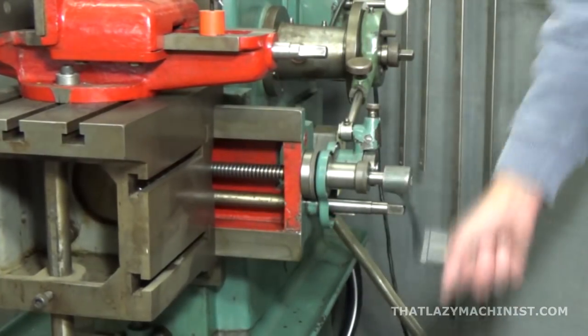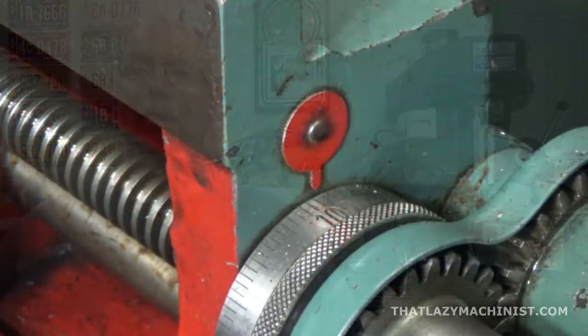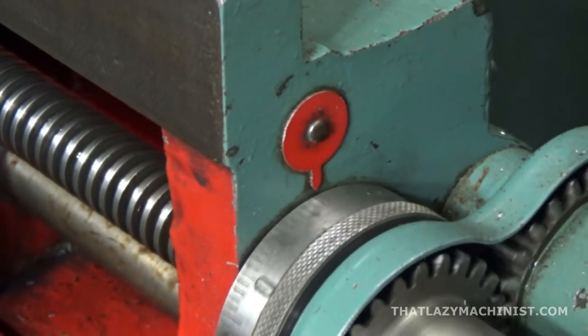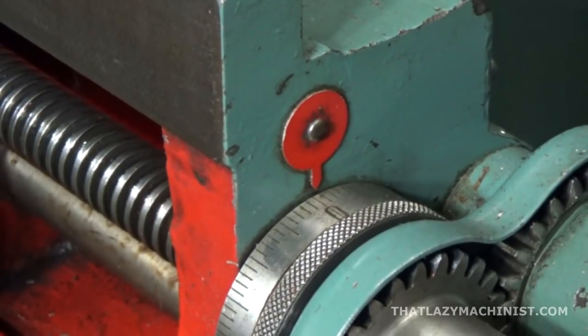The third reason that would justify using a screw thread in the machine shop, well, is accurate motion or movement. And well, we see that all over the shop with our lead screws. If we want to move the table on a milling machine, well, we can move it very accurately because we can break down the pitch of a lead screw into degrees of motion and really just adjust how much movement actually we get quite accurately.